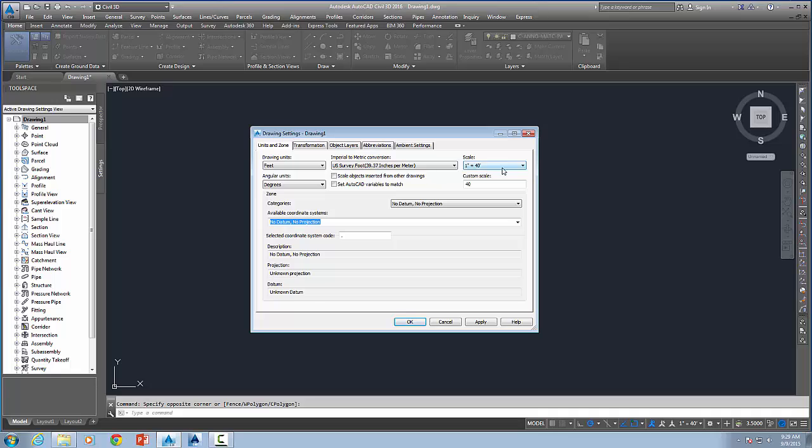And the other thing I should mention, when I say full scale in Civil 3D, it means that you're actually drawing in inches. So 1 inch in Civil 3D or in AutoCAD is actually 1 foot to us. When we put in a unit of 20, it's actually going to draw at 20 inches, but to us it's going to be 20 feet. Just keep that in mind, because if you're sharing data with, say, an architect, they're probably working in architectural units and you're going to be out by a factor of 12.